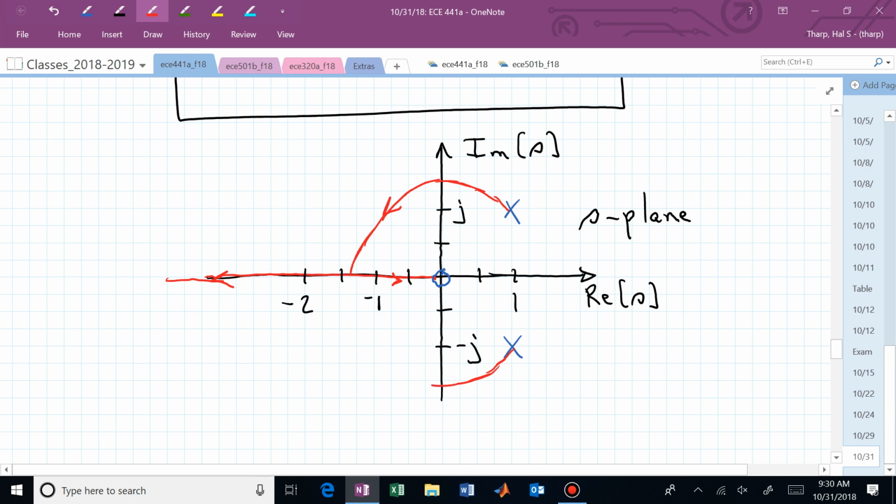It should look better than what it's looking, but you get the idea. We leave the poles, and now we come in and we re-enter the real line at the square root of 2 negative, and then one goes zipping to the origin, the other one goes zipping to minus infinity for various values of k. Questions on that?